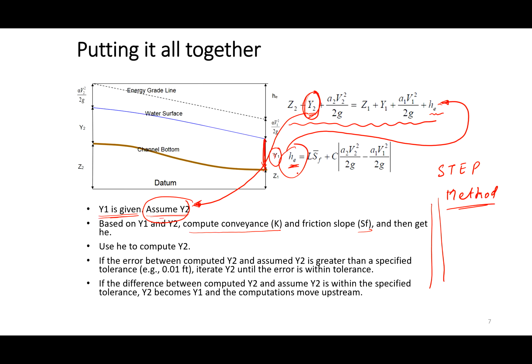Now, this is the working of HEC-RAS behind the scenes. What do we need to do for the model to actually work? For that we need to define the HEC-RAS geometry. Going back to HEC-HMS, a lot of information about the watershed is provided in the HEC-HMS basin file. In HEC-RAS, a lot of information about the river is provided through the RAS geometry file, or just the geometry file. You may ask, what does geometry file mean?